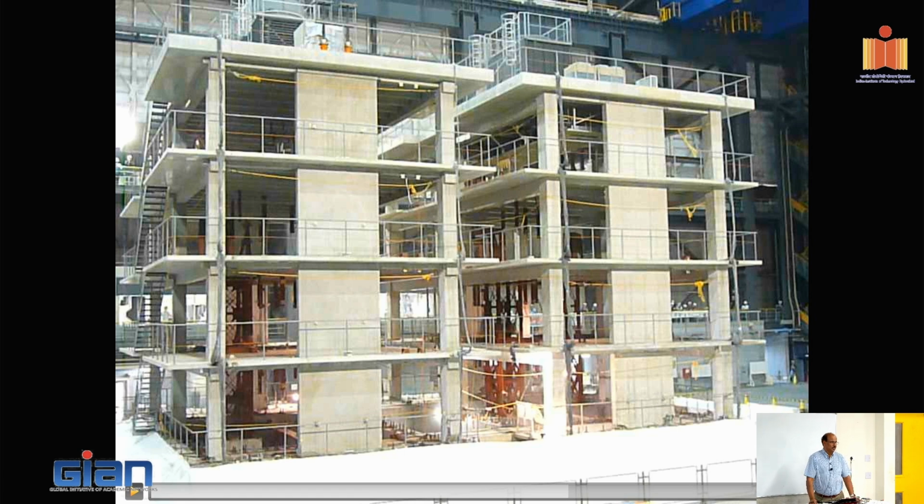They were undamaged, and then they obviously measured the residual displacement. So this was almost negligible. This one has a fairly significant amount of residual displacement as well. So you can kind of appreciate the benefit of going away from the emulation concept and trying to design this as controlled rocking structures for precast.